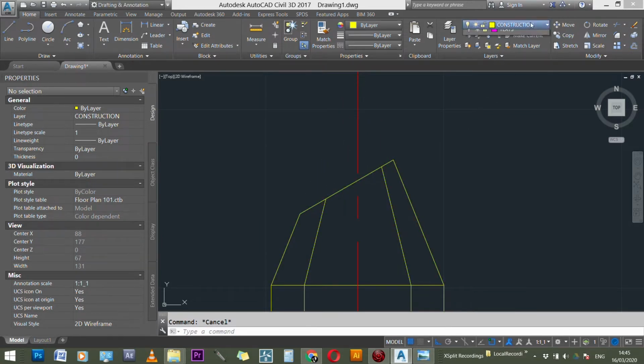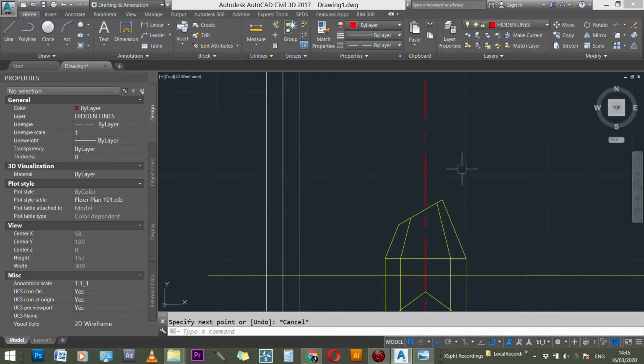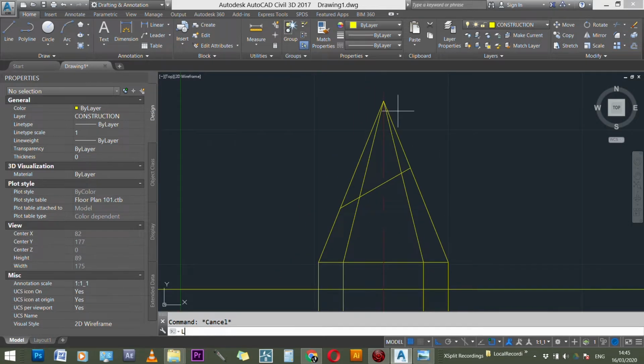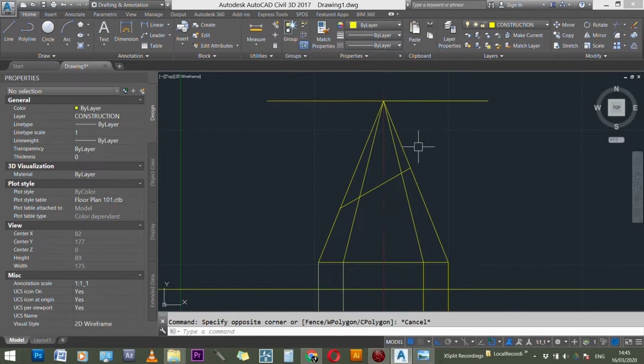And then I'm going to create some new lines under a layer called hidden. Hidden layer just indicates that these things, oh, let me just keep one of these points right here because I need to reference where these will be going. Right? So now I can remove the trim lines.